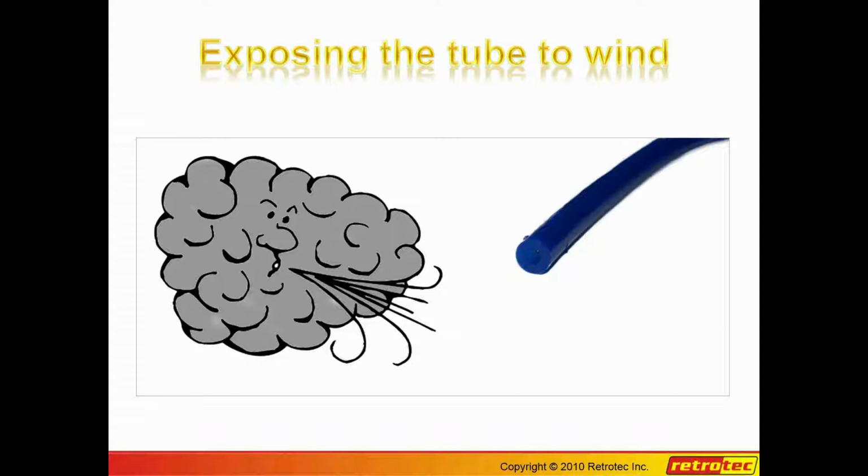I also like to put, say, a piece of 1/4-inch plywood, 1 foot by 1 foot, 2 foot by 2 foot over top of the tubes if there's any wind, so it keeps the wind from blowing into the tubes. That works better than the old trick of sticking it in a Coke bottle. The other thing is, if you look very carefully in this picture, you'll notice there's a drop of water in there. If there's any rain around, you touch the end of the tube to that water and it will immediately seal the end of that tube off.